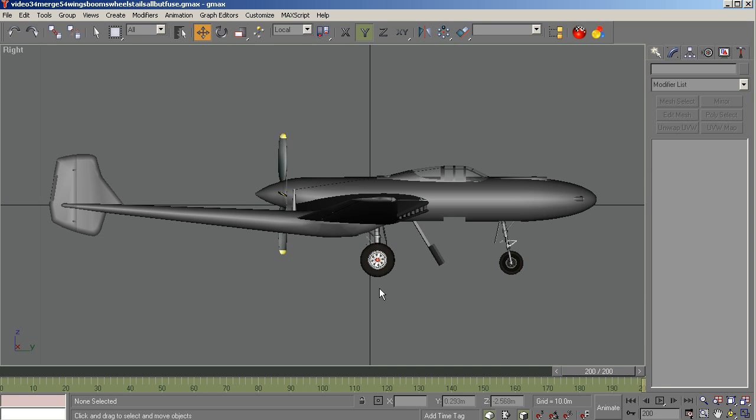The next thing we'll get is gear data. Where is this gear located relative to both the Gmax and the FS reference points? Everything in the aircraft config is done based on your reference to the FS reference point. And in my case, I always make them the same just for simplicity reasons, but they can be different. So in the next video, I'm going to come back and tell you how to collect all this data, your contact point data, how to calculate your suspension movement, and translate that into a good looking, good working suspension.